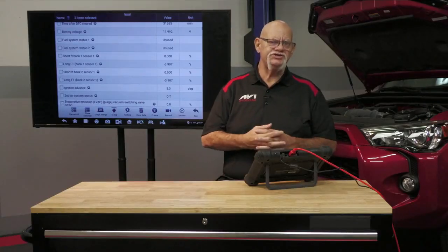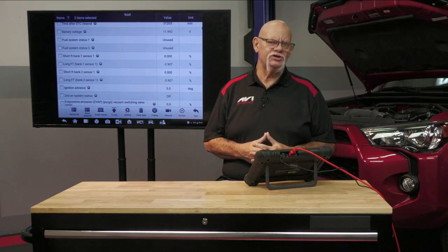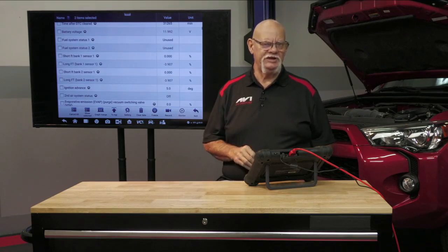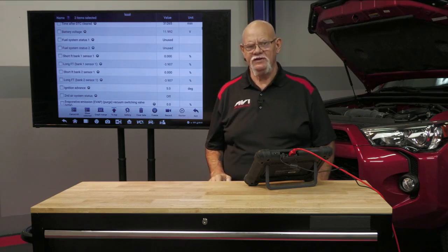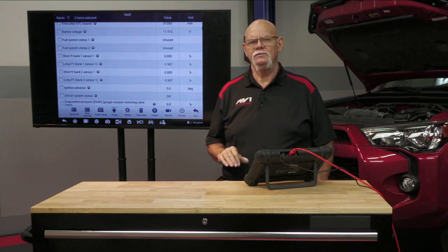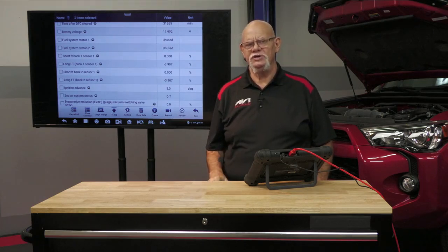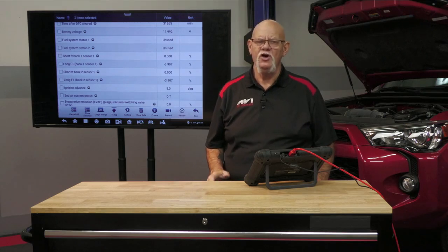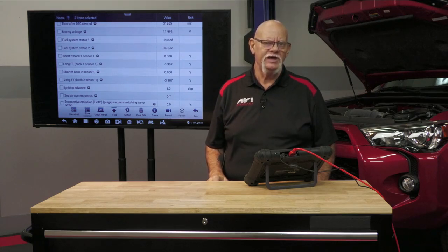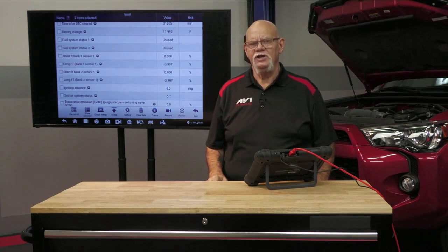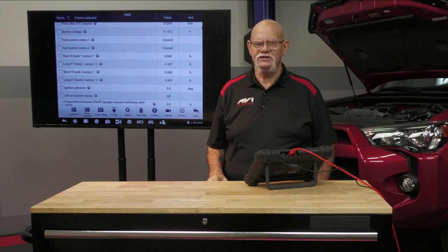Our specifications, we really want to see the short-term fuel trim floating between -7 and +7. If it's taking more latitude or adjustment above 7% positive or below 7% negative, that's a high-level indicator that I need to be more thorough in looking at the oxygen sensor. He becomes a high-level culprit of a problem if my fuel trims are above 7% positive or below -7.